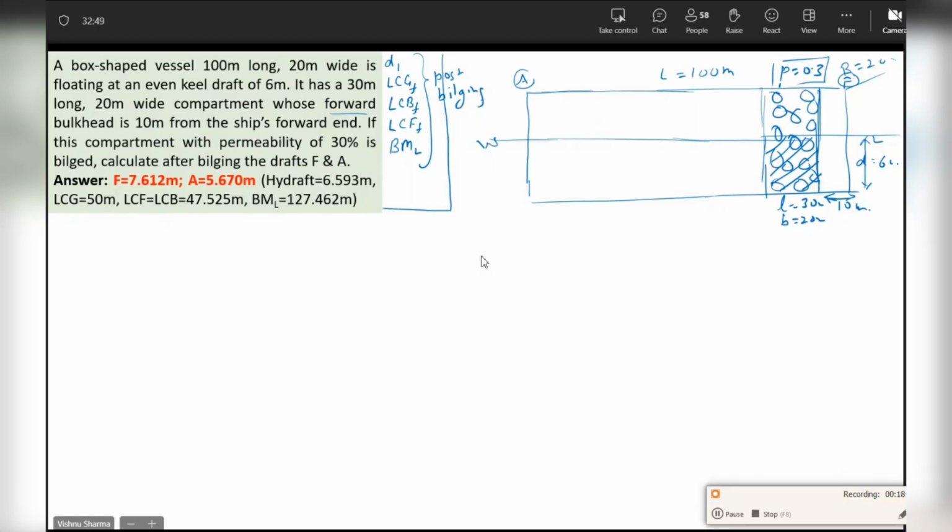I agree, the final water line will be trimmed. But we are drawing a water line like yesterday for an even keel condition. That means for D1, W1, L1, and then this draft, wherever I find space, I have marked it. So not necessarily that it has to be marked here. That is D1. When the vessel sinks, the water will rise in these pockets. So water will fill up here also. You see, these are the things I'm repeating, and if you keep doing them religiously, you will not miss out. Now I make the water plane at W1, L1.